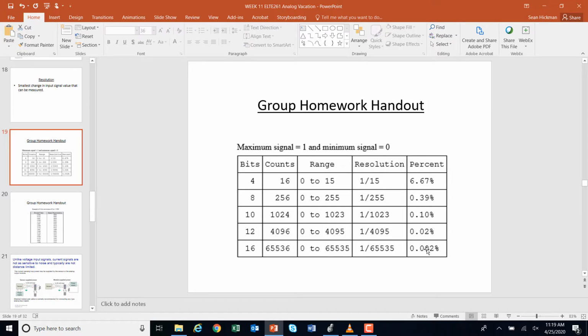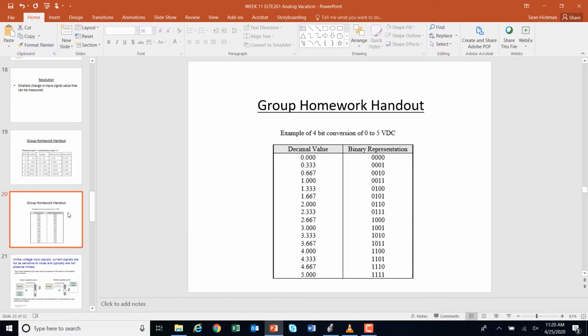and you get a much better resolution. So you get 0.00001. That can mean that little 1 can represent not very much. But if you don't have many bits, that 0001 in this case, because only 4 bits, boy, that 1 sure is a pretty big chunk here, okay? So this is going to be much better resolution. And here is an example of 4 bits using 5 volts.